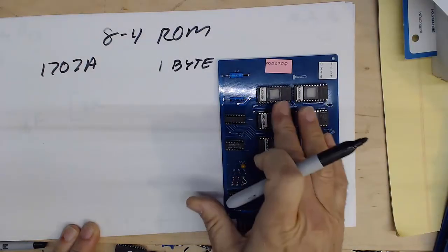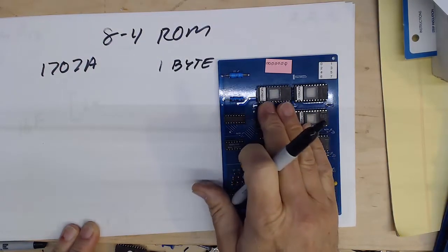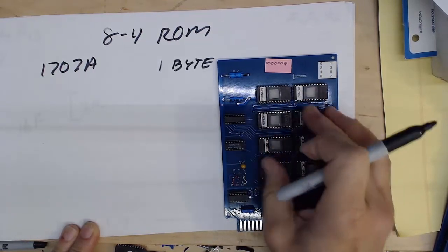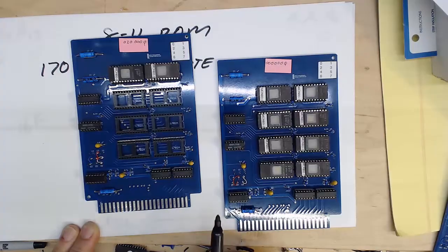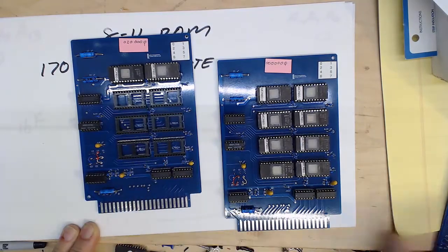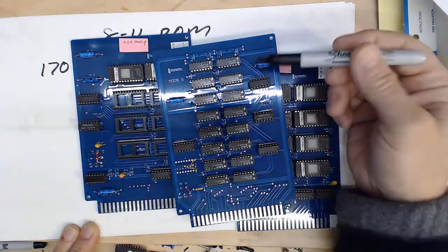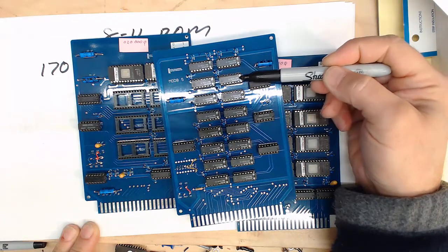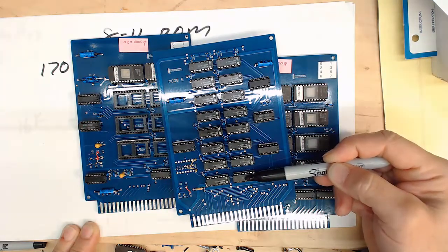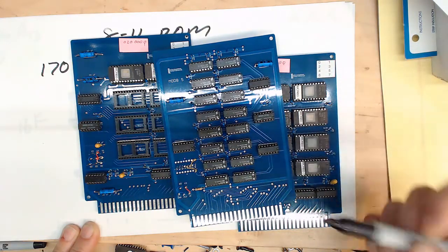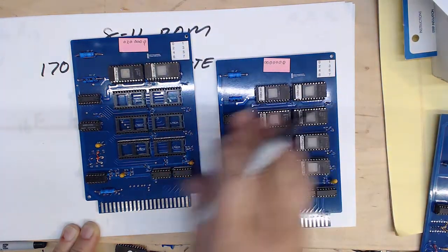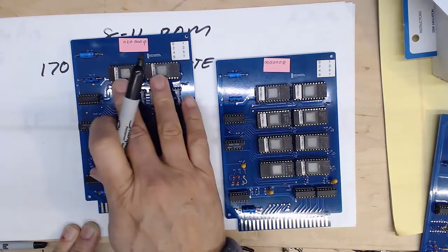So each of these chips has all 8 bits to form a byte. And so anytime that we're looking at something on this board, we're only looking at one chip at a time. What that allows us to do is we don't have to populate the whole board to get all 8 bytes. That's in contrast with the RAM, where these are 1 bit per chip. So what that means is we have to have all 8 of one group populated in order to get all 8 of our bytes. So you see, these are 1-bit chips, and these are 1-byte chips. So that's a fundamental difference in that each of these chips holds the entire byte.